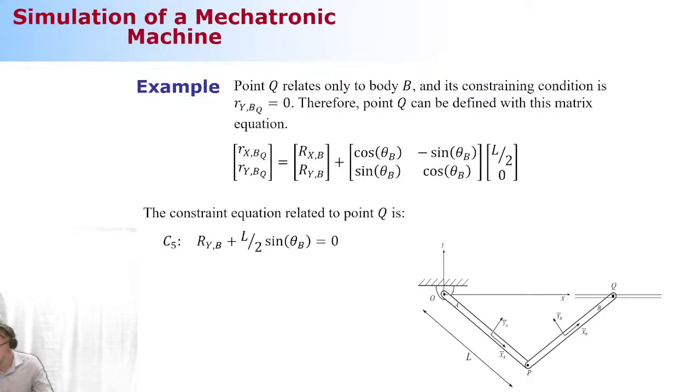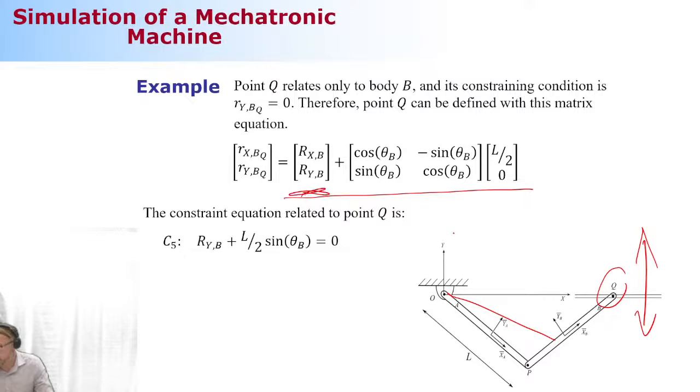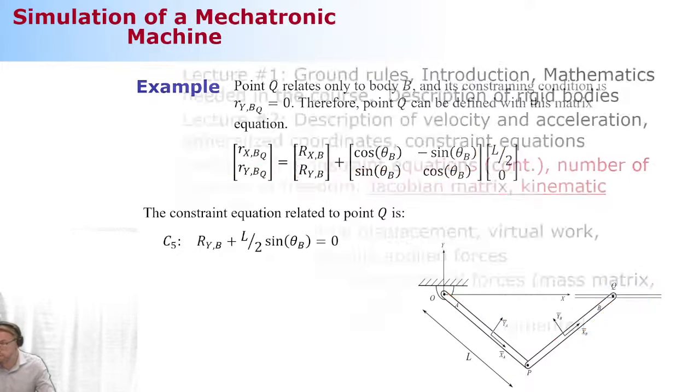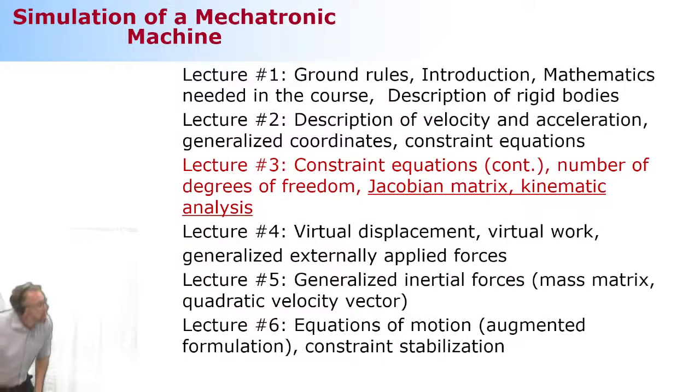Final one. This one here cannot move along the global y-axis direction. So this is where the point is located. You're going to go first here, this guy, then orientation, this one here, and then you're going to go here. This is going to be your vector u bar. And then you say that this one needs to be equal to 0 because it cannot move in the global y direction. So you take this component, this row, multiply by this. That's your fifth constraint equation.